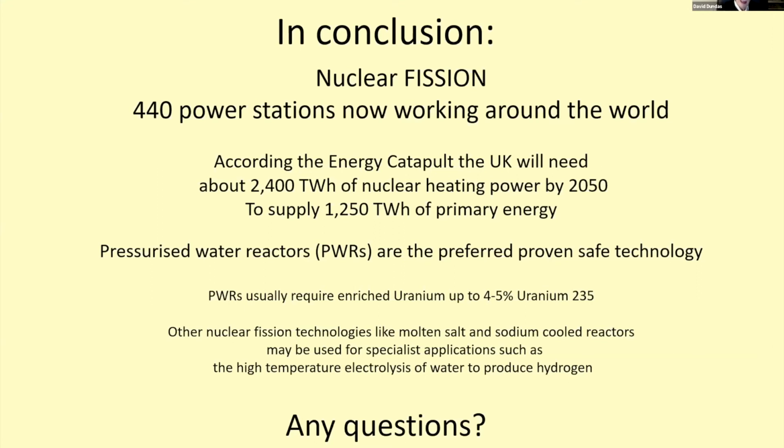And by the same token, what we can do is store the hydrogen that's produced in the off-peak times. The power stations continue to run, but instead of just slowing them down or stopping them, you can continue to make hydrogen with an electrolyzer, and then you store the hydrogen. So the whole balance of the output of power from the power sources, how you contain the variation between the peak demands and the low demands, batteries will play an important part, but hydrogen stored will also do the same thing.